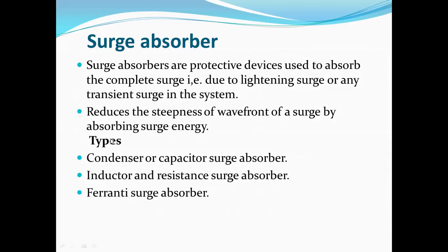Then the next point is the surge absorber. To protect these lines or any equipment from over voltages, we are using surge arresters and surge absorbers. So what is a surge arrester doing? It is bypassing that voltage and current, or diverting it. It is not absorbing.